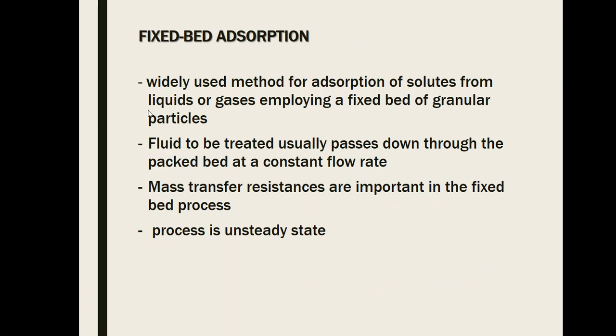Now, fixed bed adsorption is a widely used method for adsorption of solutes from liquids or gases employing a fixed bed of granular particles. The fluid to be treated usually passes down through the packed bed at a constant flow rate, and mass transfer resistances are important in the fixed bed process. Though the process is really in unsteady state. Now what then are the process variables and adsorption cycles that you need to know regarding adsorption?